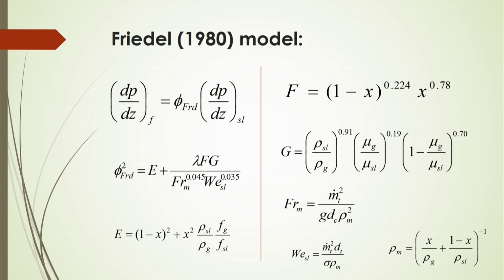Now, Friedel 1980 also developed a model based on the same Lockhart-Martinelli concept. Here again he has taken the frictional pressure drop of single phase flow, and he has multiplied it by this multiplier, phi Friedel, to get the total frictional pressure drop.